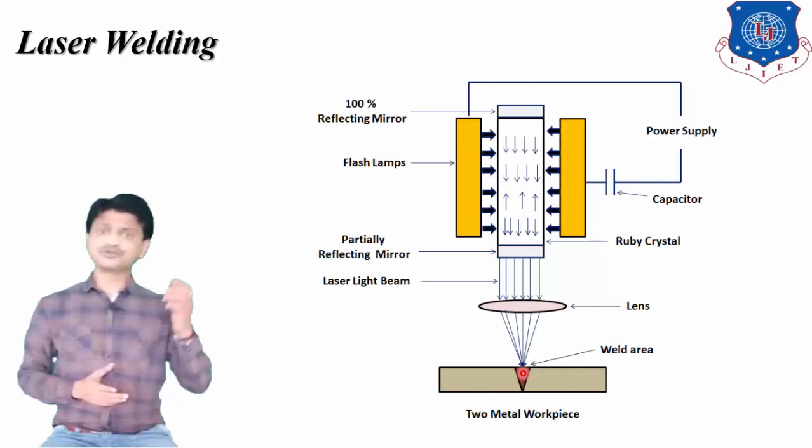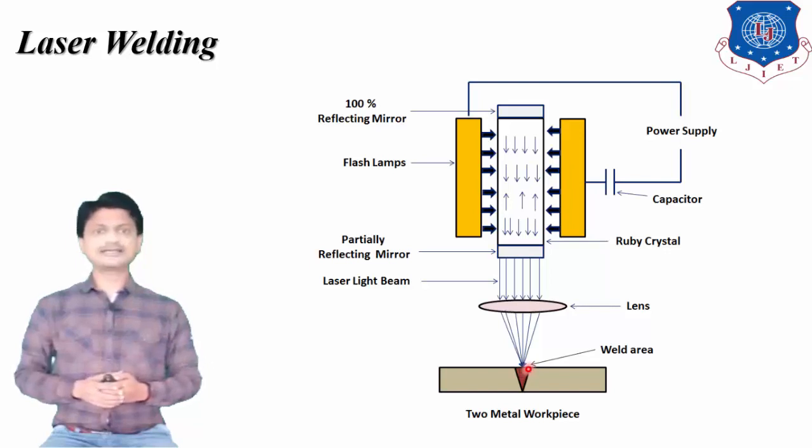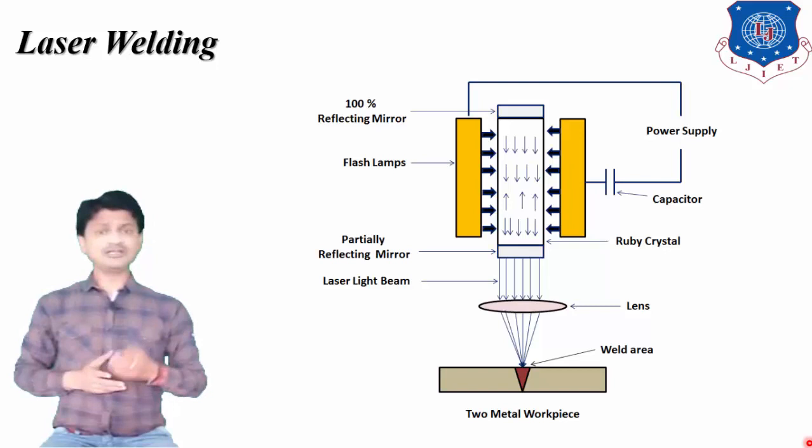Due to the high heat generated by the laser, the material melts over a tiny area on which the beam is focused. Since the heat produced by the beam is so intense, the impurities in the material, such as oxide, float upon the surface, and upon cooling the material becomes homogeneous. When it cools down, the material becomes a homogeneous solid structure, which makes it a strong joint.